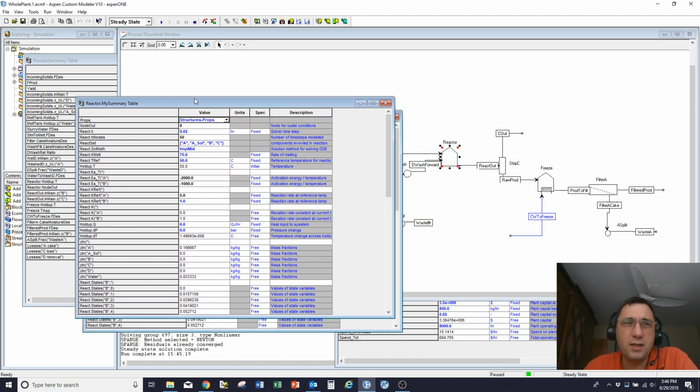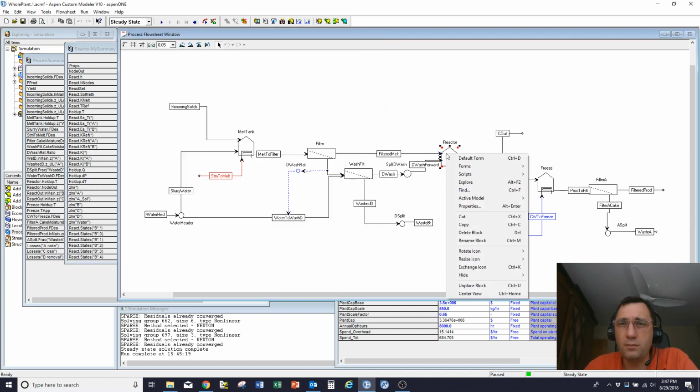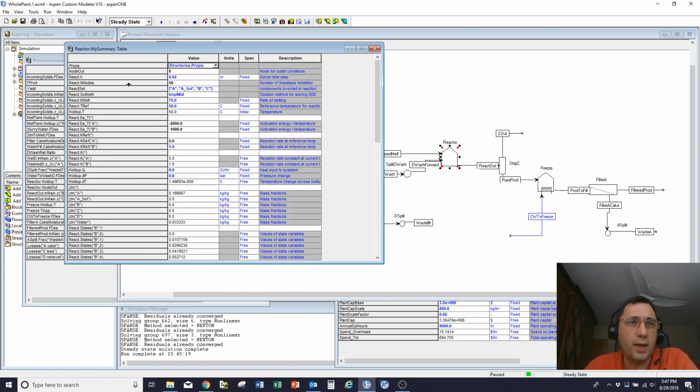What I've done here is I've cheated and assumed the reactor is a batch reactor. Rather than doing a dynamic simulation, I've broken those simple reaction conditions down into an implicit Euler method, so I can solve the dynamic component of the reactor as a series of algebraic equations, and so embed it into a steady state model. I've broken my overall batch into 50 segments, each of which is 0.02 hours long, or 1.2 minutes. So I simulate an hour's worth of time, and then I choose what point on that curve to draw out my product.